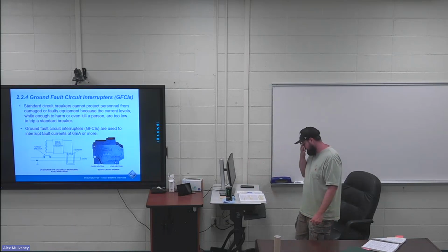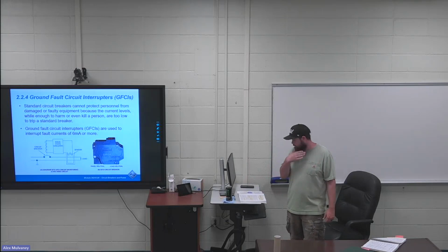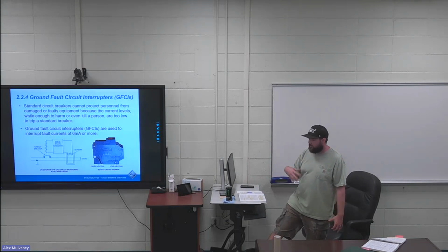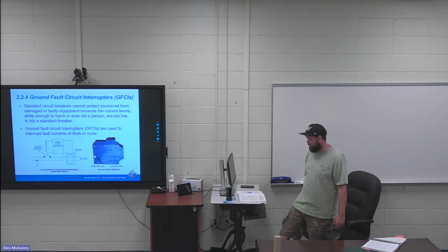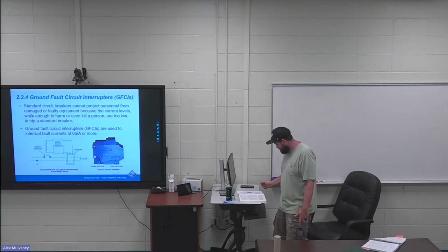It's very important how you wire up GFCIs. You have a line side and a load side. Most of the time I've seen people trying to wire this stuff up, you just have to know what side your hot's coming, or your line side is coming from, and then if you're doing the feed-through type, where that stuff is going. It's very important. If you don't get those right, they don't work right.